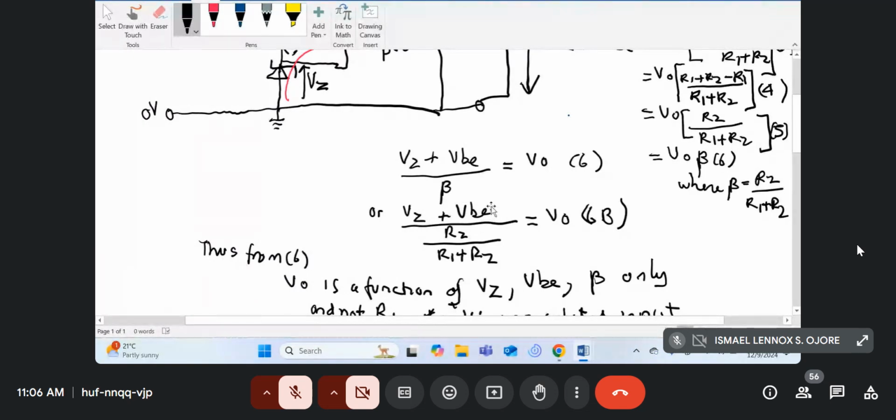So you can buy resistances with plus minus 5%. This will have the gold band at the end. You'll have some resistances manufactured to a tolerance of plus minus 10%. That will have a silver band at the end. And then you have resistances with tolerance greater than 10%. Those ones will have nothing.